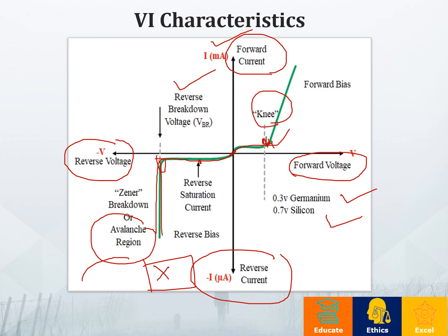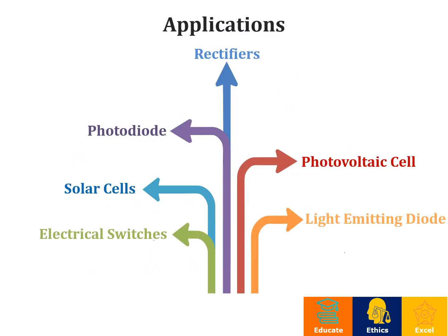So it is very evident from the voltage-current characteristics that only under the forward bias condition will my PN junction diode start increasing the current. Whereas in case of reverse bias condition, there will be a steep decrease in the current because the width of the depletion region is higher, and there will be a flow of a reverse saturation current.